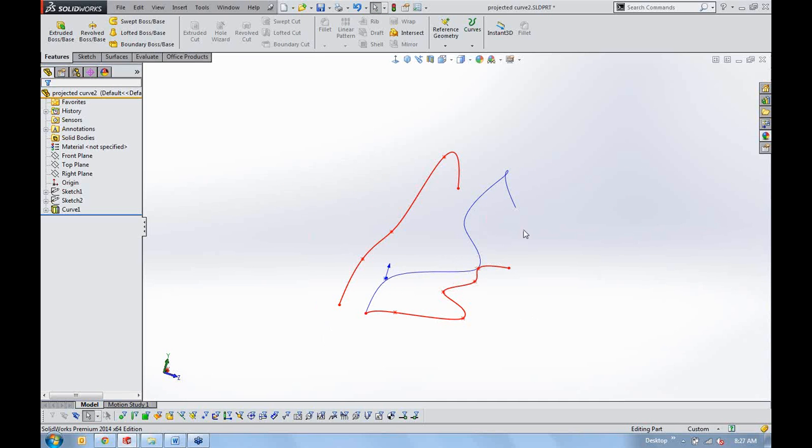So basically, you can use this as a boundary edge, right? So I would do it for this one, maybe for the bottom edge, and then maybe loft or fill surface between the two, or boundary surface between the two, or multiple ones. So those are again kind of a tool that gets a little bit underutilized, and it gets you very complex geometry very easily. The setup is very easy, and it's easy to control now, right?